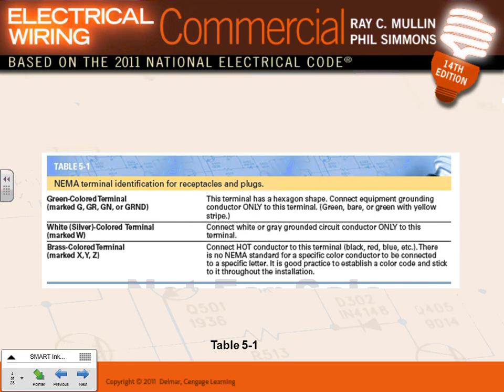How do we eliminate them, Joel? With the spec. The specification coming from the engineer always says commercial grade spec receptacles, meaning we want the heavy duty type 15 and 20 amp receptacles. Can I have a thumbs up, Chad, that you understand that one?